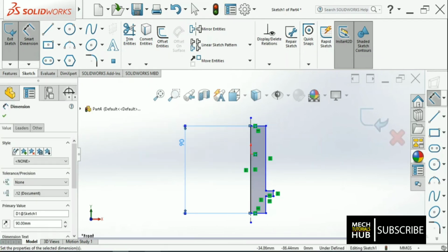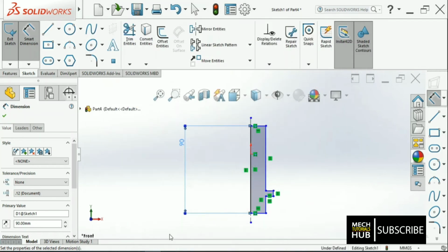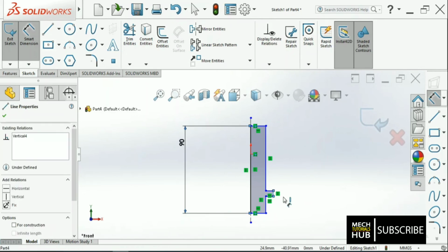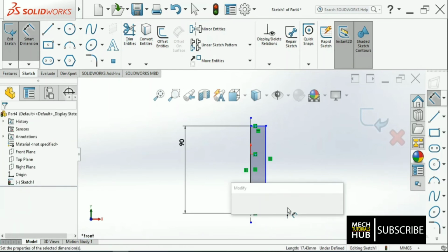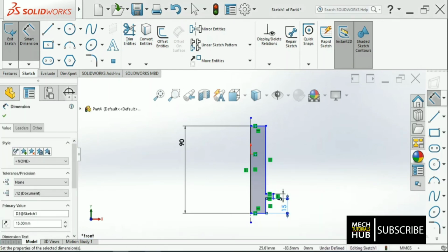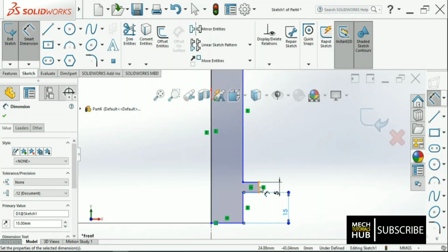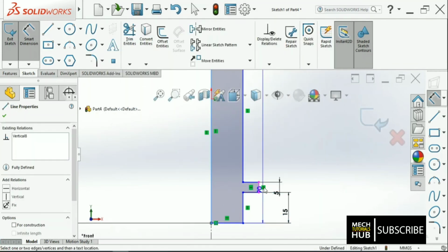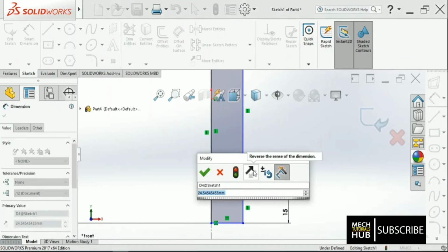That is fine. Again here the thickness is 5, bottom height is 15, thickness here is 5 and bottom height is 15. This is also fine. And anything else that we have forgotten, that we need to check. Yeah, this is 24, means 12 mm. This distance, this is 12 mm. From this line to this vertical it is going to be 24, 12.